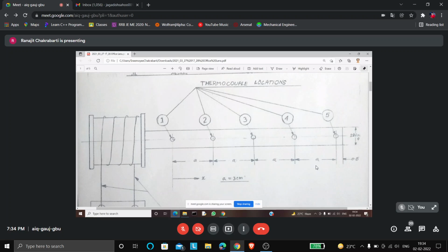We are assuming that if you consider any circular cross section, the temperature is uniform at all points of that cross section. If you cut it, at all points in that circular cross-sectional face the temperature is considered equal, because we are neglecting heat transfer in the R direction. So all the points must be at the same temperature. With R there is no variation of temperature.